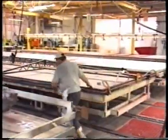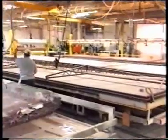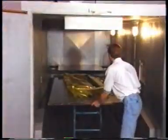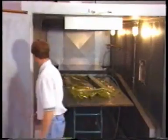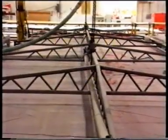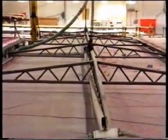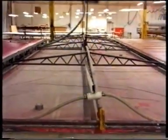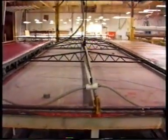Once full vacuum is applied, the mold is allowed to cure at room temperature or transferred to an oven or autoclave for curing. Vacuum is usually maintained during the entire heating and cooling cycle. Vacuum bag molding is effective in producing relatively large and complex shaped parts, including those having compound contours.